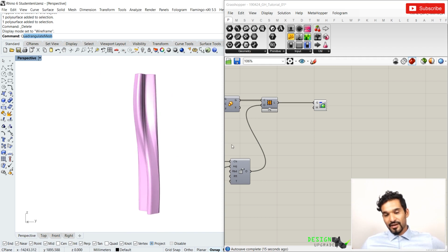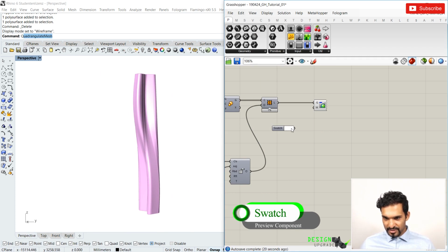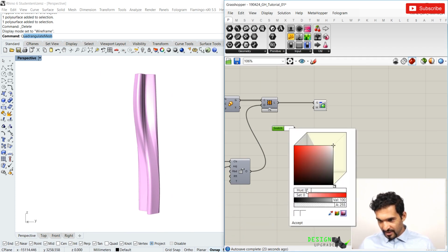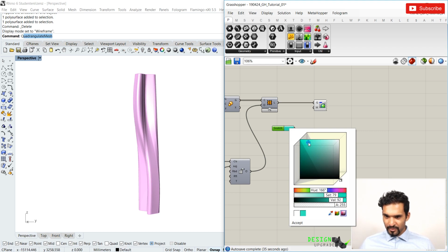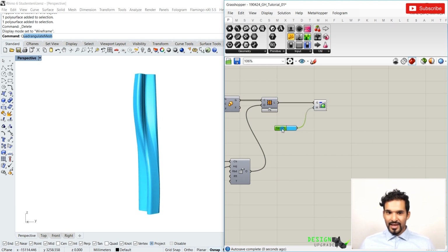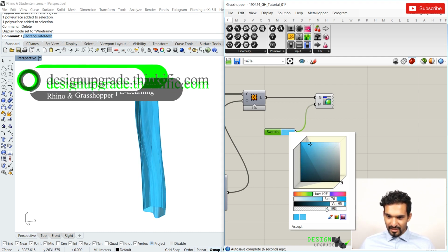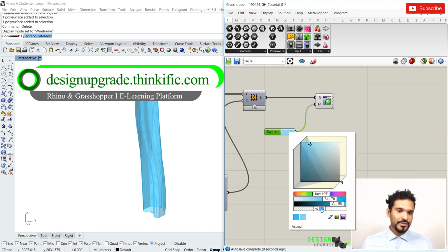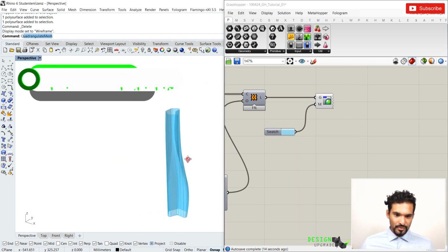And if I want to change the color, I can use a swatch, which is a common way to do that, right? So a swatch is just a color picker. You just click once and you can then literally decide which color you want to take with the hue saturation value, or you can also change into RGB mode. But I'll actually work with the hue saturation because it's a bit more intuitive for me to just cherry pick whatever color this should be. So for instance, like this, and I have now defined my tower here. I can also press on this and adjust alpha, or basically just control the transparency here. So let's make it a bit more transparent, and we can see now this is actually kind of working in a nice way.